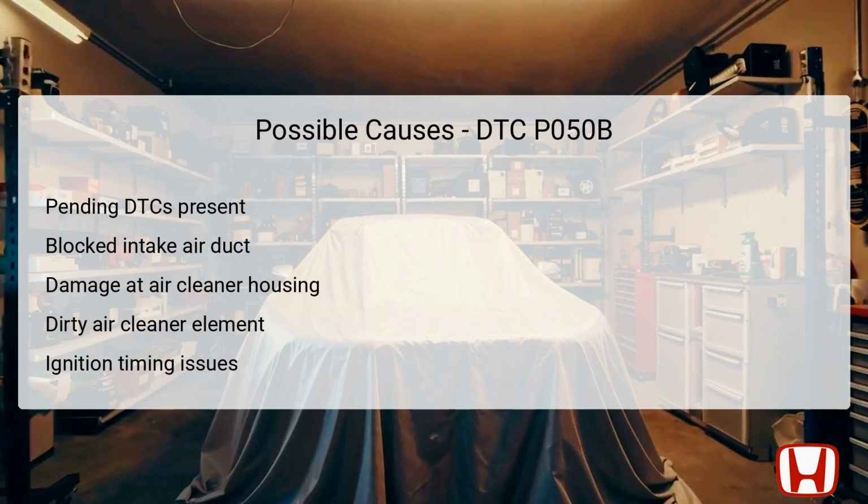A dirty air cleaner element can also hamper the engine's intake process, necessitating either a replacement or cleaning to ensure proper function. Furthermore, misconfigured ignition timing may arise from issues with the CKP sensor or other related components, impacting cold start performance. Each of these elements plays a vital role in maintaining engine efficiency, particularly during cold startups.